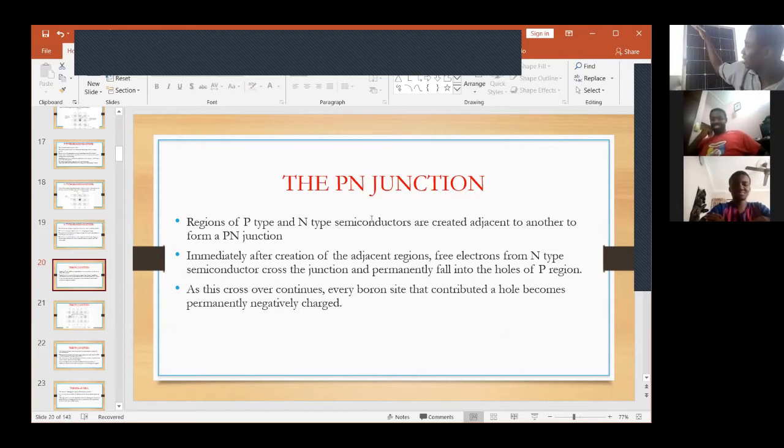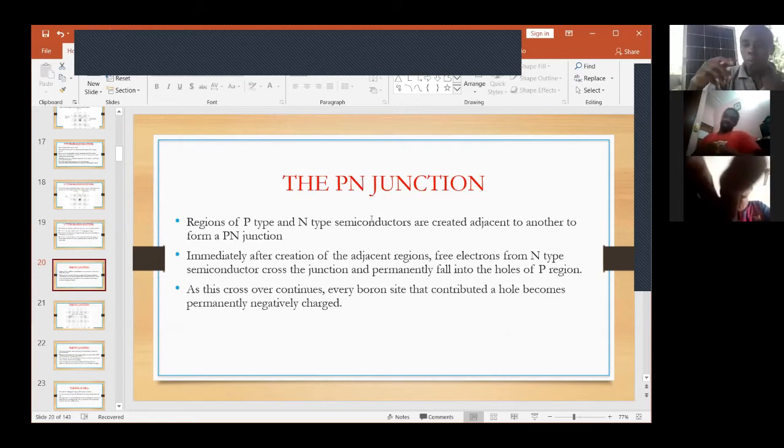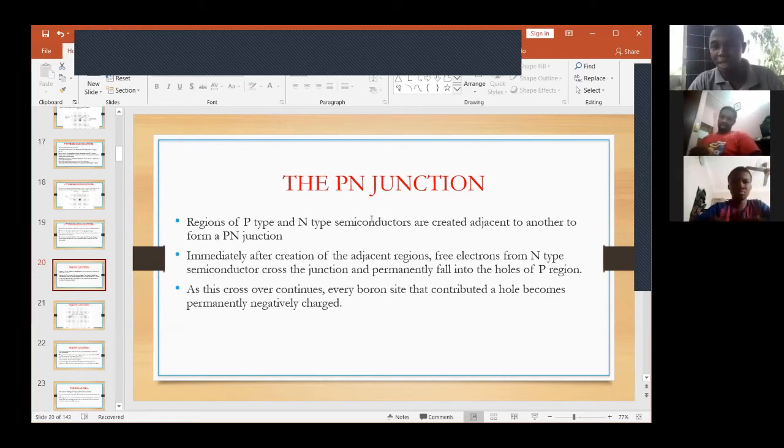So what we are saying is that as big as this 100-watt panel is, if they had used the 6 watts per cell, it would be just half this size and still generate 100 watts, because they would only need to add 18 cells instead of 36. And they will still get the result. Because each one is a PN junction, and a PN junction has a standard voltage.